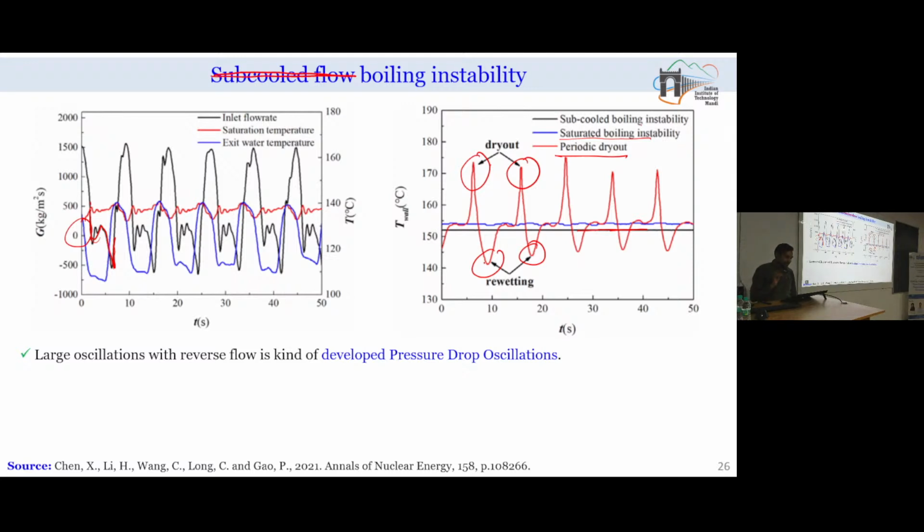So, these are some of the issues which one needs to address with natural circulation flow boiling before their implementation in actual industrial or practical systems, because if we do not address such issues, then though the idea was to avoid accidents which could take place because of the failure of the pump, these may actually cause accidents if these instabilities are not avoided.